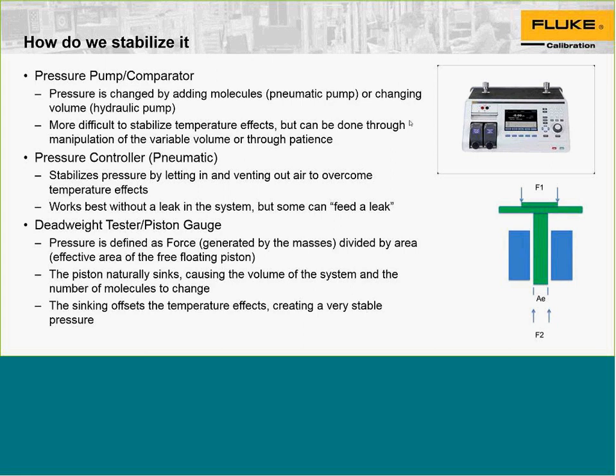As you pull up on the lever arm, air is drawn in from the atmosphere and then pushed into the system as you press down again. Or the pressure is changed by changing the volume of the system, like with a hydraulic pump. With a hydraulic pump or comparator, it's more difficult to stabilize out the temperature effects, but it can be done through manipulation of the variable volume or through patience.